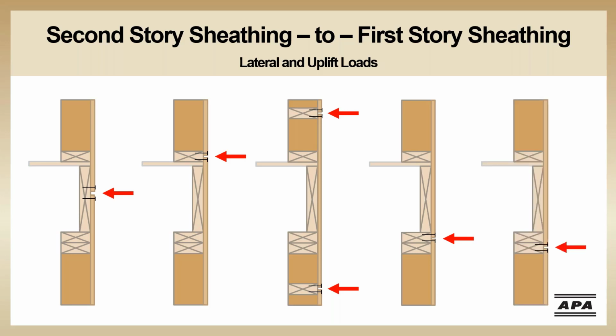But keep in mind, as we discussed earlier, the sheathing should never be fastened to only the lower top plate at the roof level. At this location between 2 stories, attaching the sheathing to the lower top plate is okay, as long as both the upper level and lower level sheathing are attached to it. All of these options qualify as common framing and will effectively transfer the wind load between the panels on its way to the foundation.